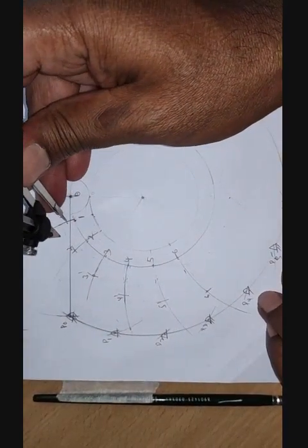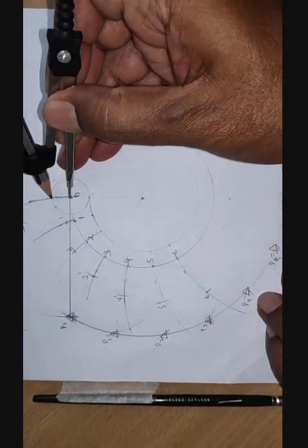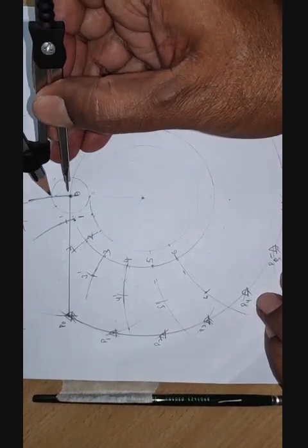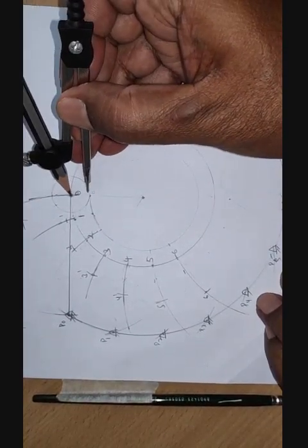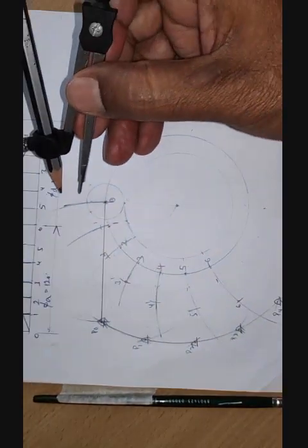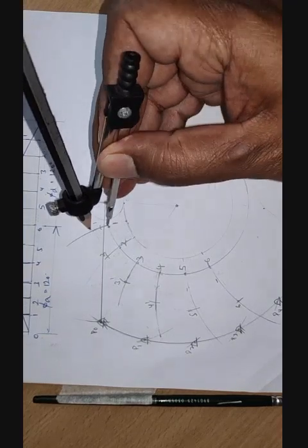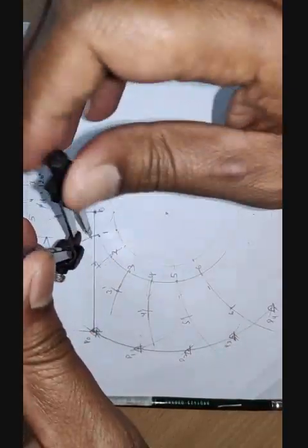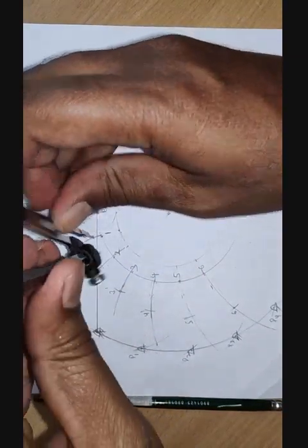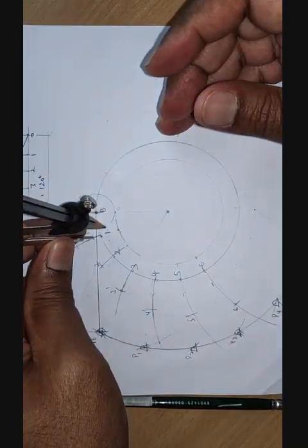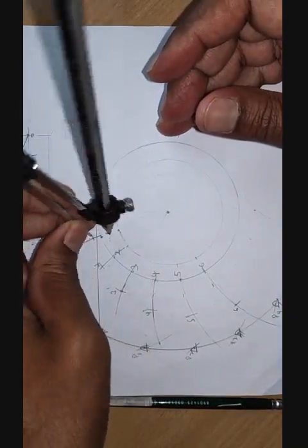So once this is drawn, then I take the same roller radius here, and here the center of the roller is shifted by a distance from 1 to 1 dash after 20 degree. So the roller center moves from 1 to 1 dash. So I take the roller here. I don't have to draw the complete roller like this because it takes a lot of time, and it's not easy. So what I will try to do is draw only the roller at the bottom like this.